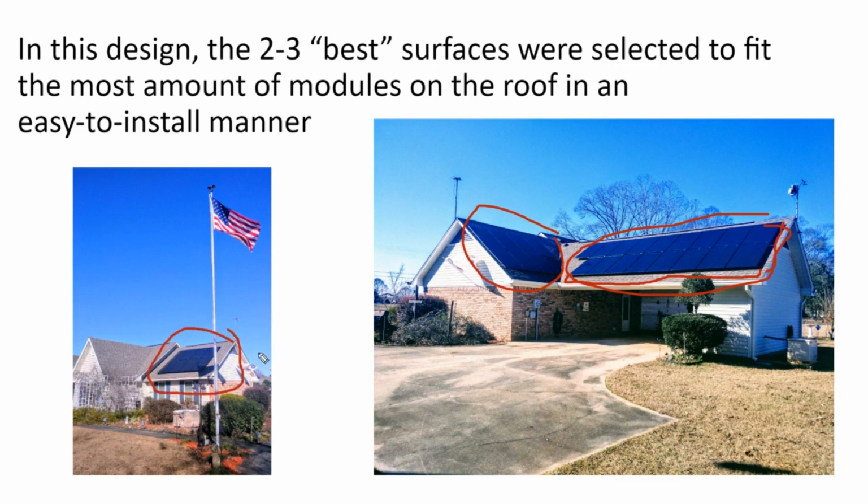Of course, more difficult installations are possible and occur regularly, but solar panels do require some maintenance access. So failure in the safety electronics could take a solar panel offline until someone gets up on the roof and puts hands on it. A long period of time without rain could result in dust and pollen accumulation on the array surface for cleaning. Proximity to a dirt road can do the same. So rooftop access is useful simply for cleaning the solar array before any other maintenance issues are considered.